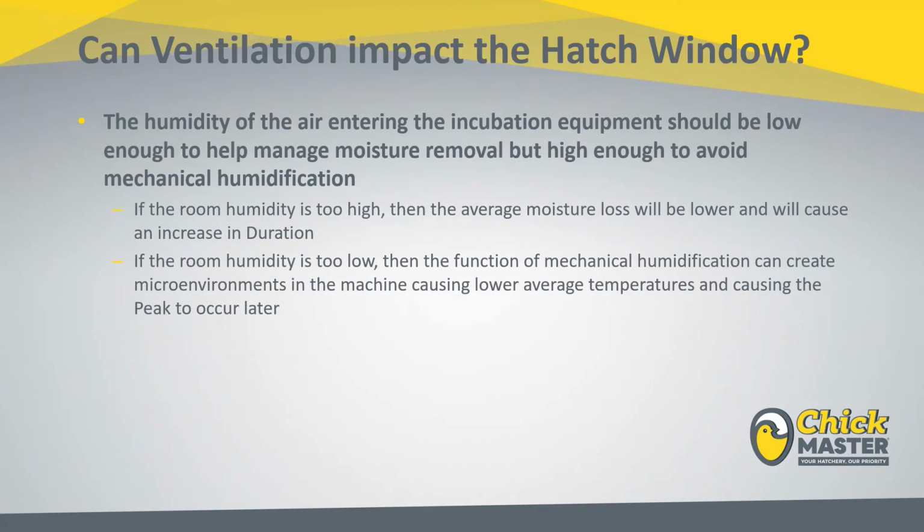And that's where we get into a situation where the microenvironments are created, especially not so much with single stage, but especially with multi-stage incubators. So the key there is to manage a good humidification system in your room where the ventilation is provided to the incubation equipment, and therefore you avoid it in the machine itself.